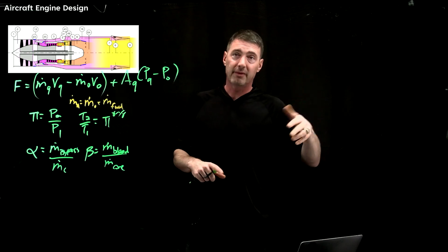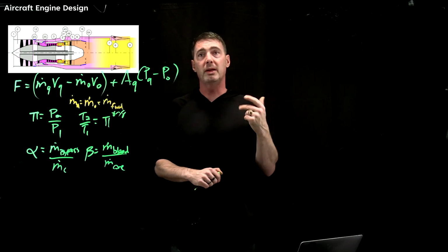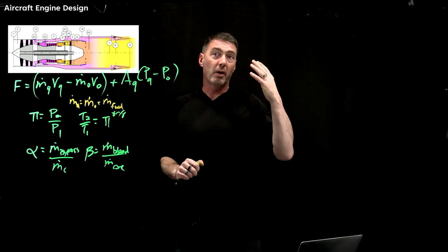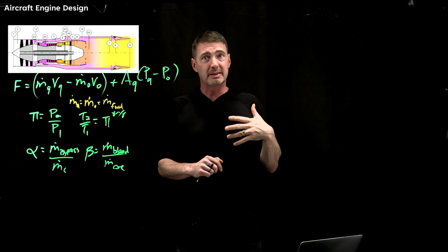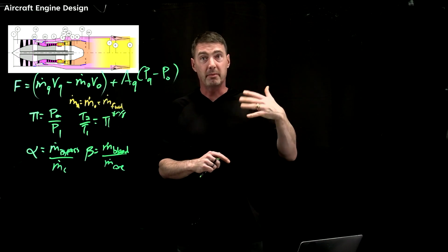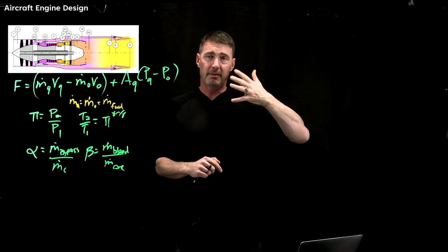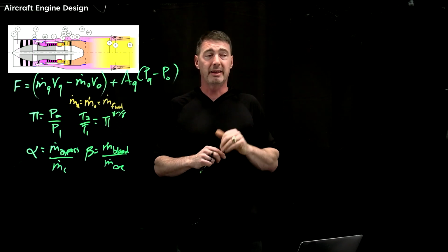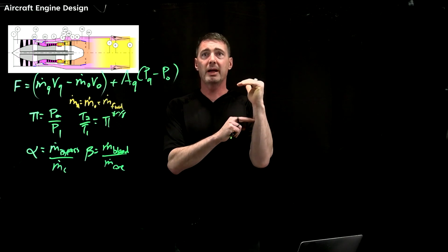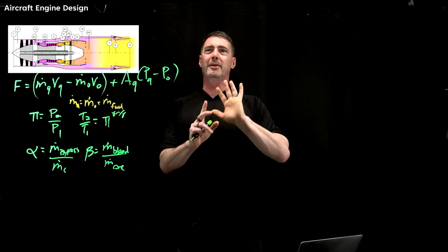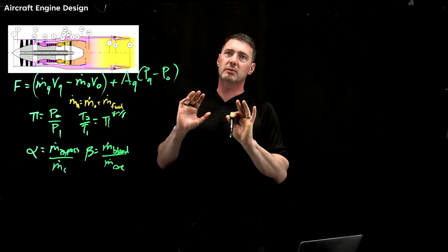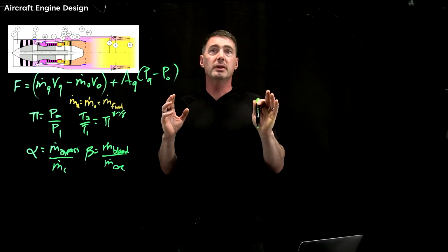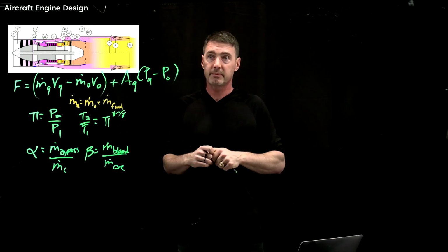The higher temperature eats into the lifetime of the engine, and so there's quite a bit of cooling technology that goes into those turbine blades, from internal cooling with bleed air, as well as what they're made out of. There are some pretty advanced technologies there. GE has done a lot with metal matrix composites. There are thermal barrier coatings on those blades a lot of times. Some of them are single crystal growth, so that when they're spinning at these rates, it's very controlled. Anyways, we'll get into all of this. Honestly, the turbine engine is one of the most glorious feats of human ingenuity and engineering ever. It really is. You're going to see why.